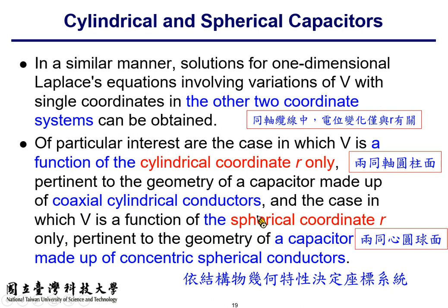According to the definition of TV channel, each channel occupies a bandwidth of 6 megahertz, and between the channels you have another 6 megahertz spacing. So from 40 megahertz to 1000 megahertz is divided into about 120 channels. In the old time, the maximum limit for cable TV channels was about 120.